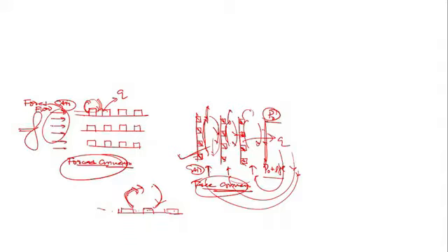Now how is it possible to have mixed convection in this case? When I use a fan here, this fan will blow the air. If I place the fan in between the circuits, then what happens? That will restrict the flow due to natural convection. When I use the flow, that flow will assist the buoyancy force.